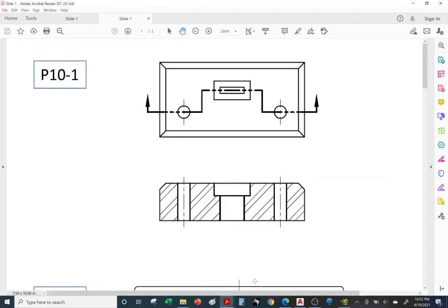So this is what we're going to draw using AutoCAD. We're going to draw our top view, and we're going to use a section cutting plane to cut through the first feature, which is a plain simple hole. Then we're going to offset, and cut through this counterbore hole, but instead of being circular, it's rectangular. So this is a rectangular counterbore hole, and it's not circular. And then we'll continue cutting through, offset again, and cut through this third feature to expose that it's a simple